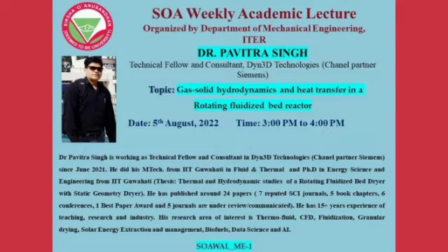So actually during this period the grain remains still wet, and free moisture from the grain surface is evaporating, and B is the point of critical moisture content. At point B the moisture removal rate ceases to be constant, and the falling rate period starts from B to C. During this falling rate period, the vapor pressure of the particle surface falls below the saturated pressure, and the internal moisture of the particle starts evaporating. This graph is given by Mazumdar in 2007.